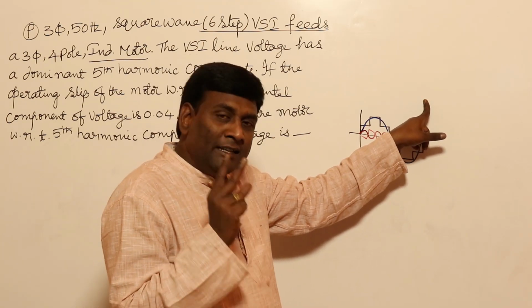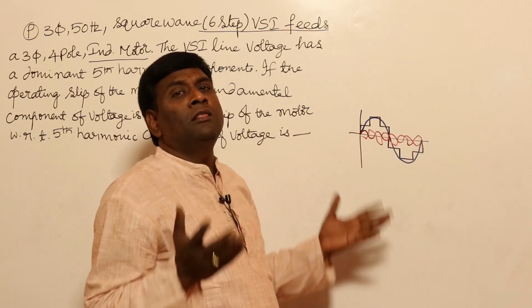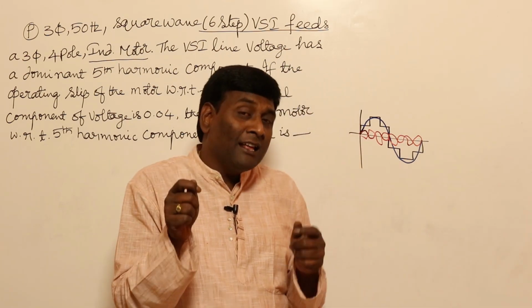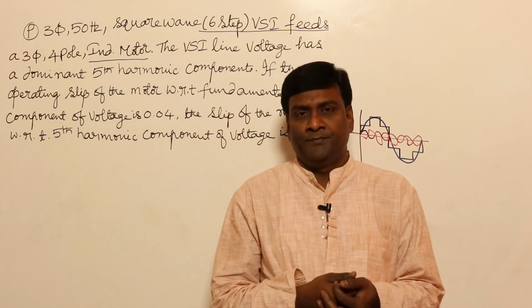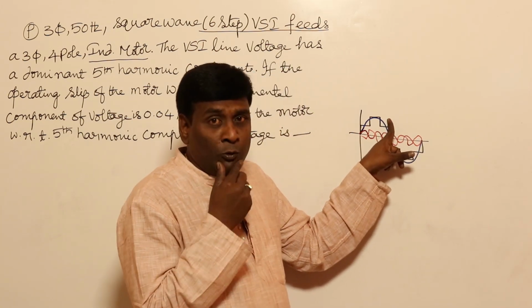In the induction motor, fundamentally the motor will interact with all the rotating magnetic fields, because independent of the relative velocity between stator MMF and rotor, torques will be produced. That is one thing. So with respect to the fundamental also, torque will be produced in the rotor.